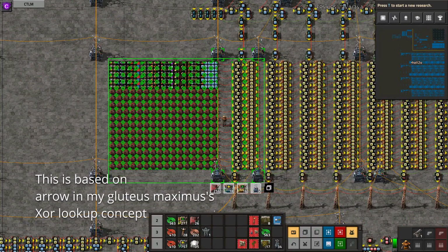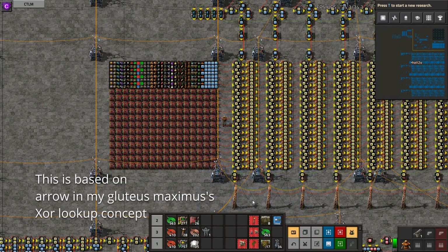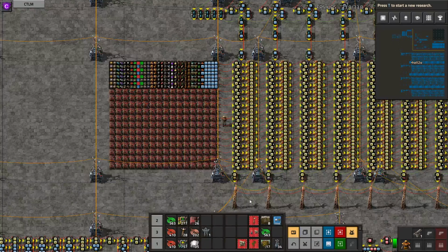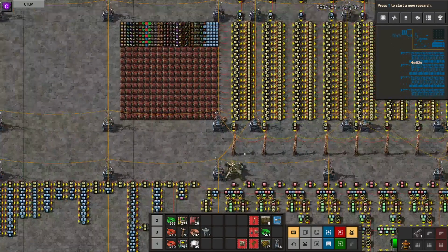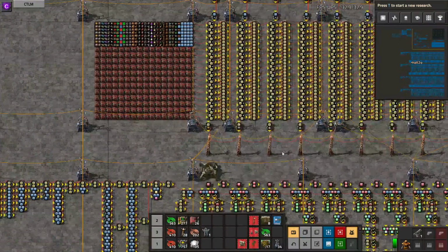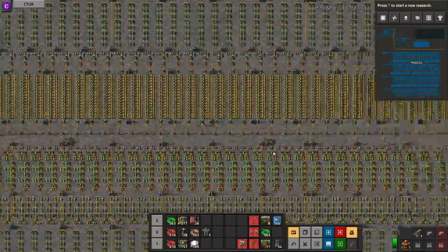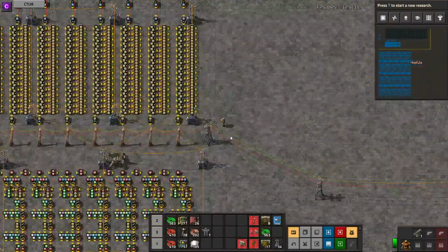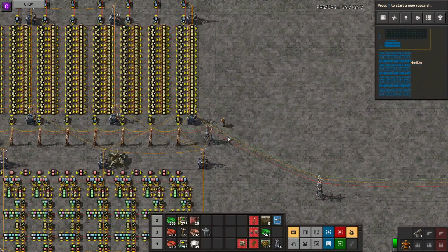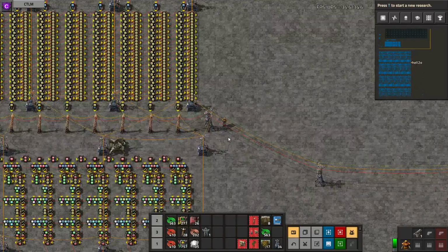So now we do a lookup for each pixel to find out what that maps to. And now we're done. We have the colours for each pixel ready to be drawn to the screen, which, again, I'm not going to explain as it's basically the same design as before, except I'm no longer packing data for multiple pixels into each channel, which makes wiring a bit of a pain, but means that it'll be easier to adapt if I want to connect a different screen design.